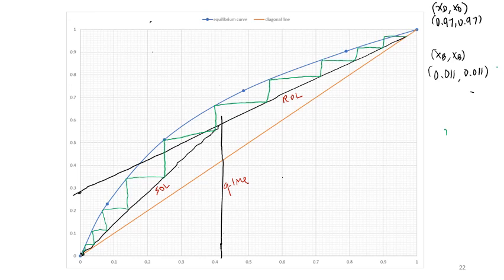So you count from number 1, 2, 3, 4, 5, 6, 7, 8, 9, 10, 11, approximately 11 ideal stages. Okay, but please don't do it like this. Please use the proper ruler, straight line, vertical and horizontal. Okay, so that is for part B, to calculate the number of theoretical stages, including the reboiler.